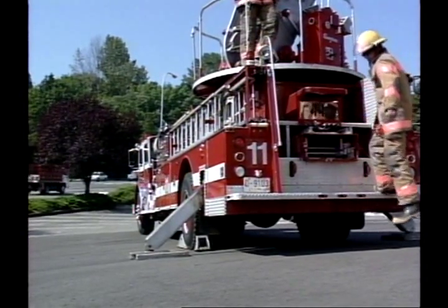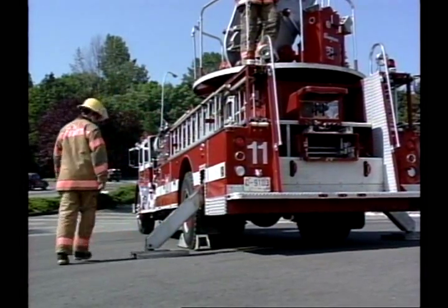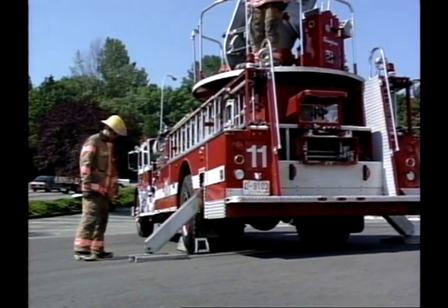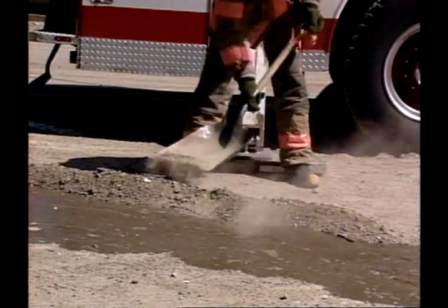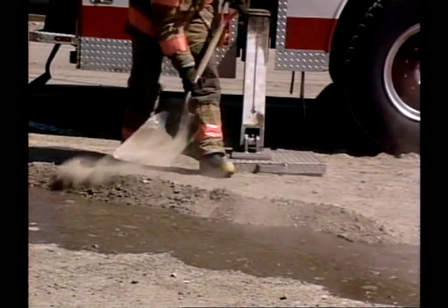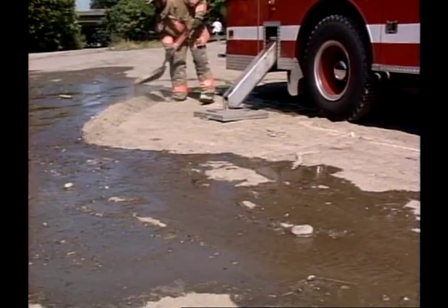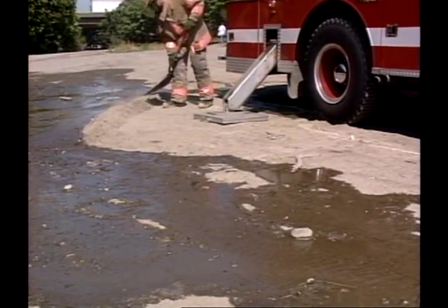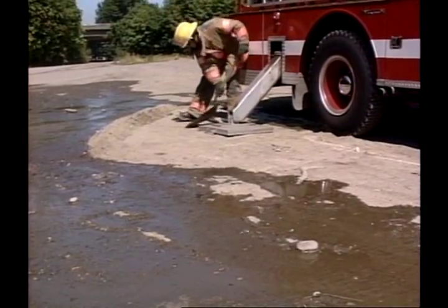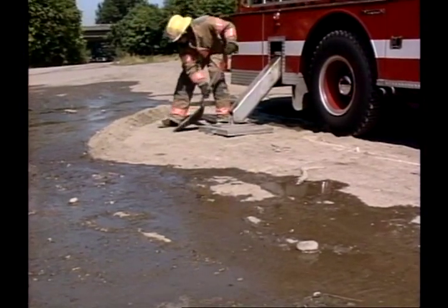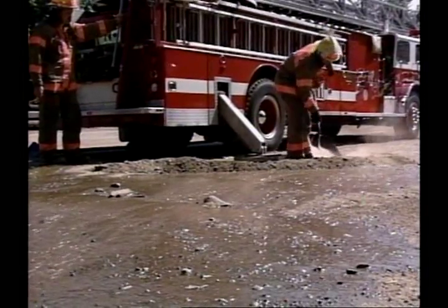Whether on even or uneven terrain, always check your outriggers from time to time to see if they need adjusting. Remember that changes can occur in the surface. Water from runoff can cause the ground to become soft, causing the outriggers to sink and become uneven. One way to avoid this situation is to divert the runoff from the truck area. Also, icy conditions, soft soil, or a punched-through paving surface can all cause an outrigger to become unstable.